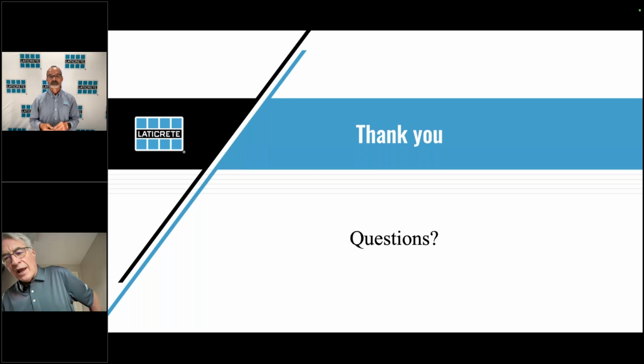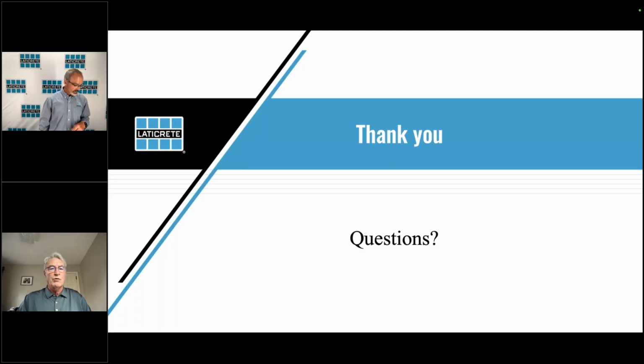Okay, how are you hanging the riser on the steps? I heard you say attaching it to the metal piece from above, but how would you actually hang or connect it? So basically, you'd take a piece of angle iron, for lack of a better term, and move it depending on how thick your material was. Let's say you had 1 inch thick material, which is pretty normal for these settings. You'd set your angle back 1 inch and adhere it here, and then the angle comes down. If I can only make a square with my hand. So then it comes down, and you're going to attach it right underneath that. And the bottom of it, you basically are going to put on the top of that bottom plate.